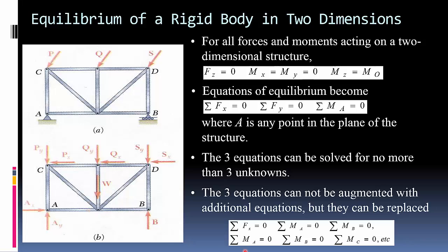If you substitute, say, a sum of the forces for a sum of the moments, that's fine, and then sometimes it's easier. But be aware that when all is said and done, it's 3 equations and 3 unknowns. You're not going to magically come up with a way to solve for 4 unknowns. It just can't be done. And so even though you might not ever take the sum of the forces in x, by taking the moments at different locations, you are effectively doing that.